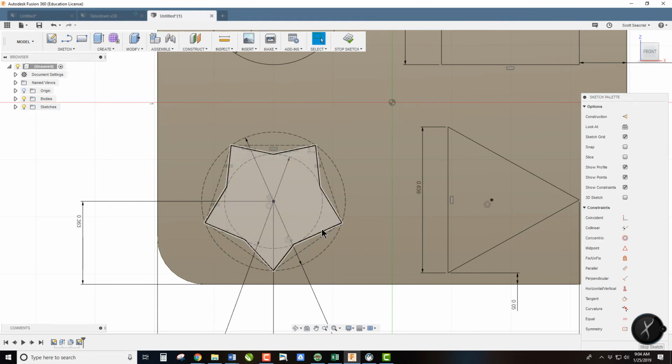Now these ones are causing me problems because they're black, so we're going to delete them. Do another set of lines. What it meant is for whatever reason I attached them somewhere where they shouldn't have been. Let's try the equals again. And there we go. Now we have this fully constrained.